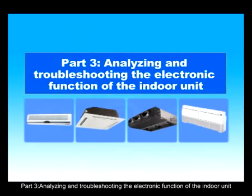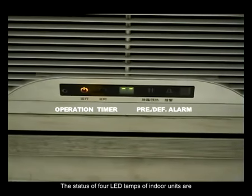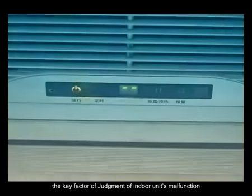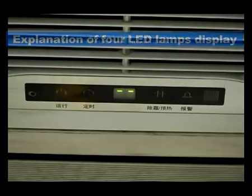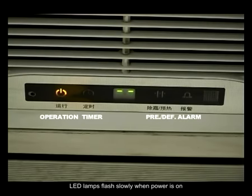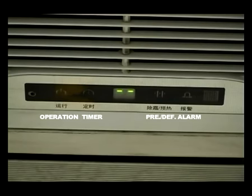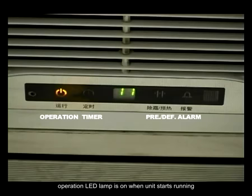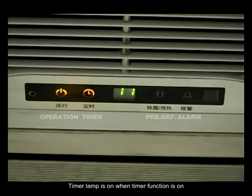Part 3. Analyzing and troubleshooting the electronic function of the indoor unit. The status of the 4 LED lamps of indoor units is the key factor in judging indoor unit malfunction. Explanation of the 4 LED lamps display. LED lamps flash slowly when power is on. LED lamps are all off when indoor units are in standby mode. Operation LED lamp is on when the unit starts running. Defrost lamp is on when the unit is in anti-cold air or defrosting mode. Timer lamp is on when the timer function is on.